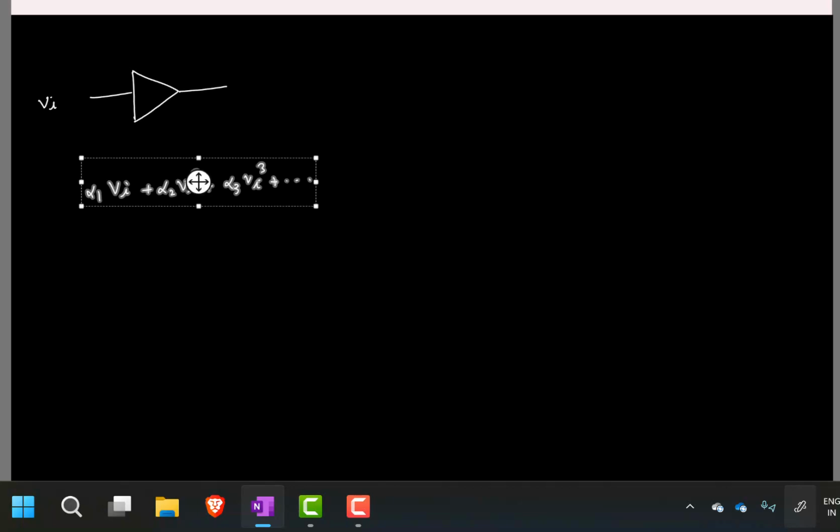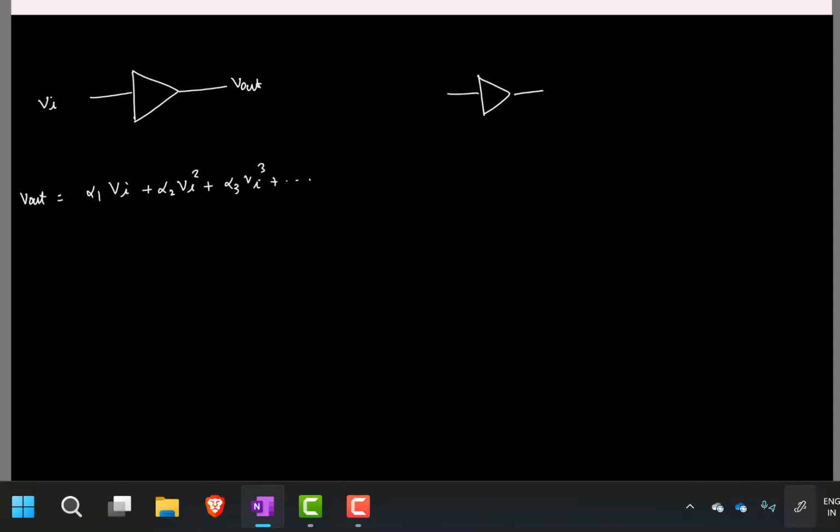Now we are looking at fully differential circuits. So let us say I form a fully differential circuit using this guy. The way we do is we take these two guys, form two differential halves, but we add something for getting common mode rejection, and we have been doing it by adding some tail source.